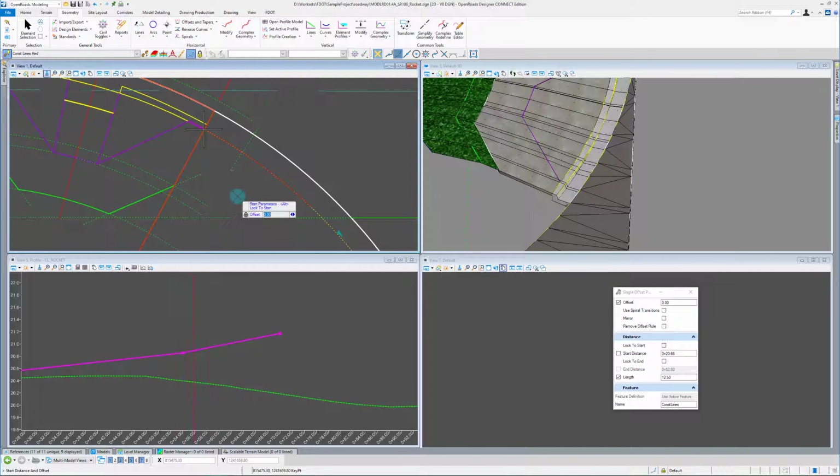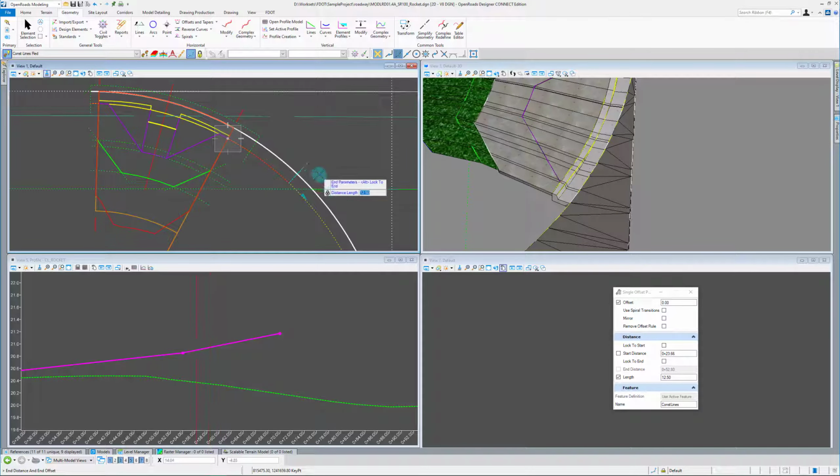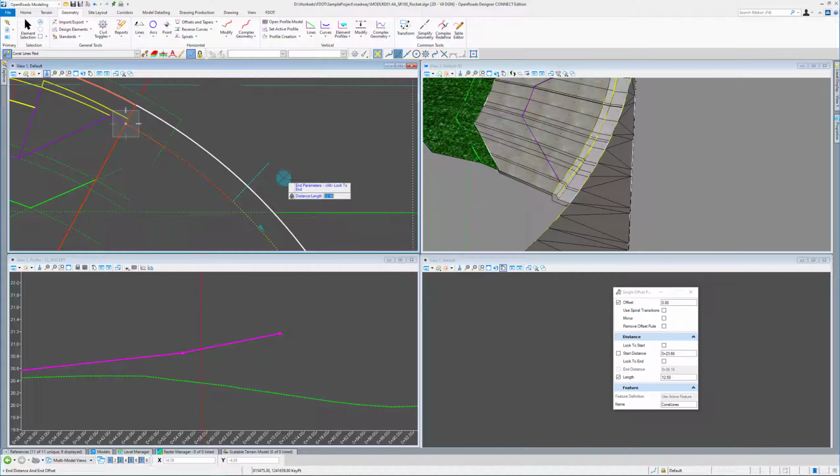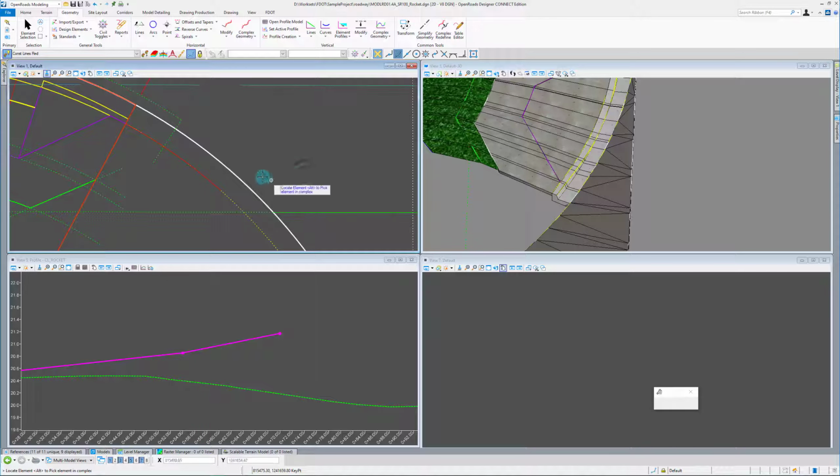So we're going to snap to there. So I know I need to go 4 feet plus 7 feet for the ramp down. And I know that my civil cell is based on the near edge of that. So that should give me what I need. So 4 plus 7 is 11. So I can snap to there.